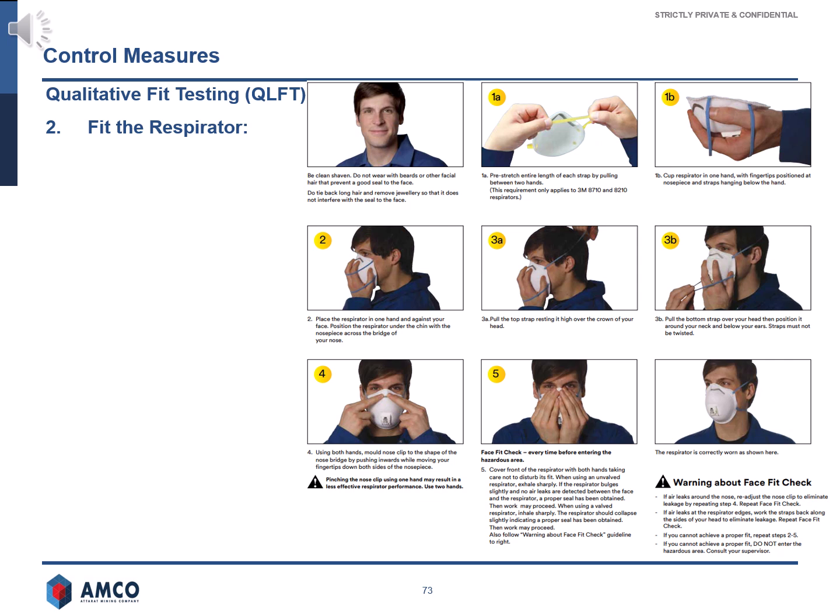Face fit check. Cup both hands over the front of the respirator without disturbing its position. Inhale sharply, a negative pressure should be felt inside the mask. If air leaks around the edges, reposition the straps or adjust the tension until no leakage occurs. If you cannot achieve a proper fit, do not enter the area requiring respiratory protection.